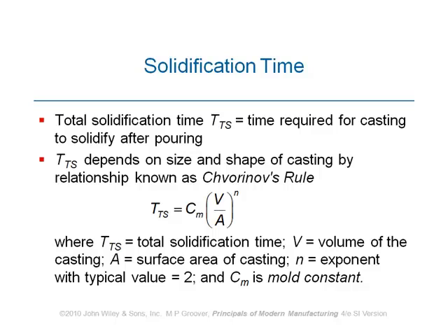Always, there is residual stress left in the material when it is subjected to heat treatment or hard working. If you want to get rid of that, put the material in the furnace, elevate the temperature, and leave it for some time. It does act as a stress reliever and elongates the lifetime of the part.